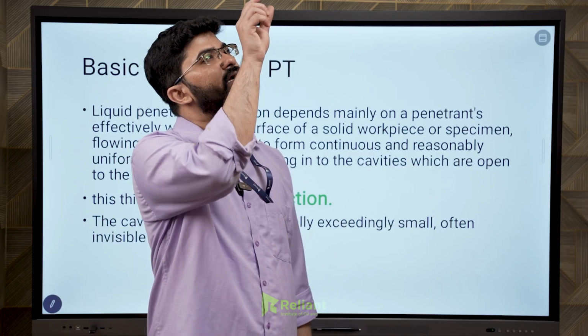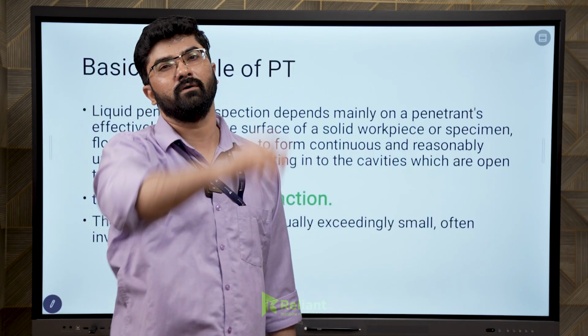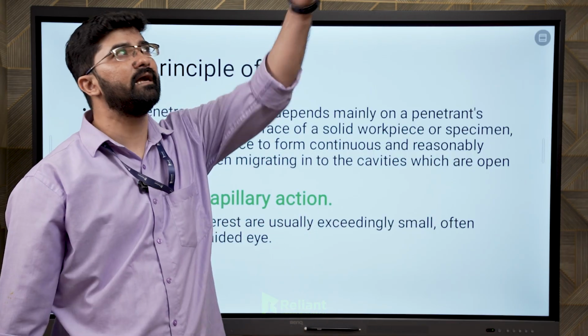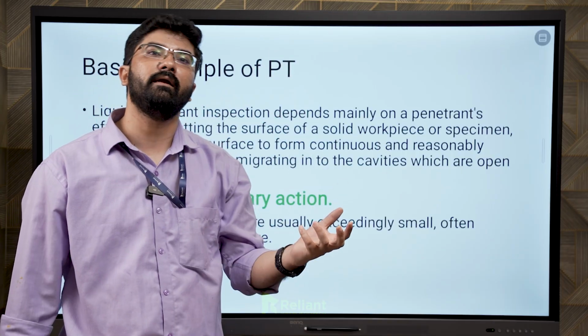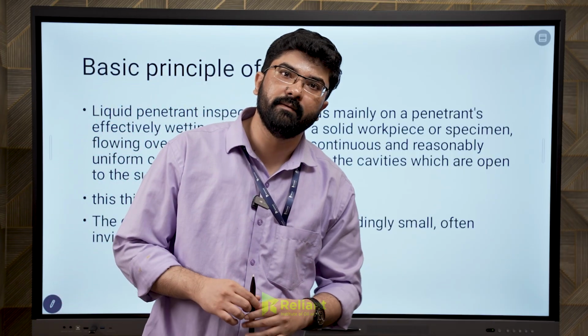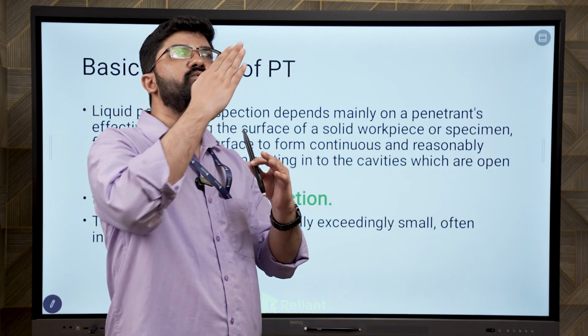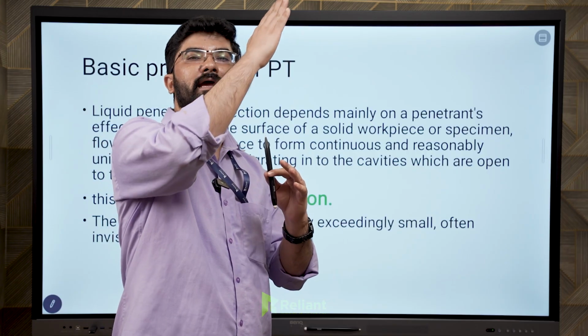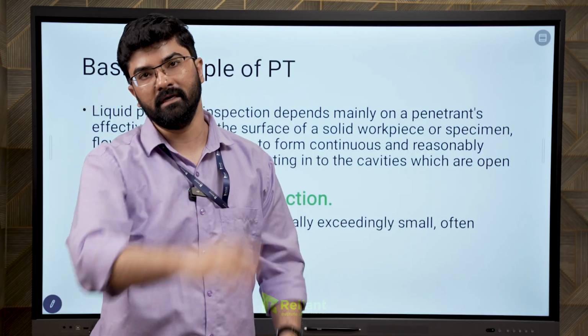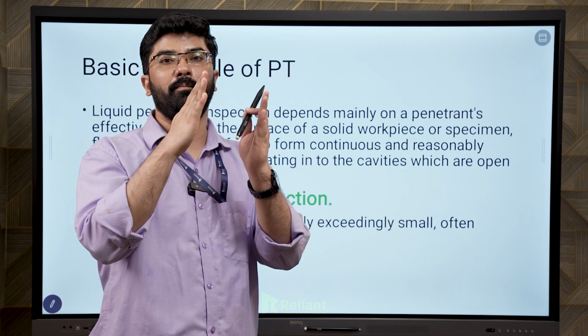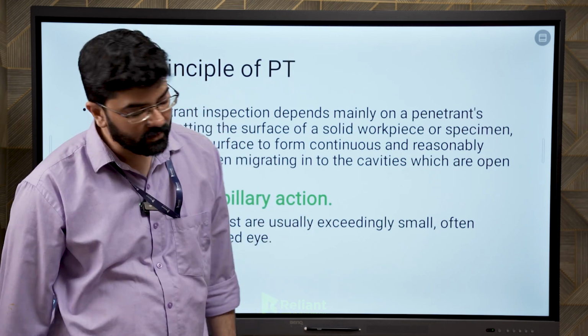In structural welding, above the head, we call it an overhead position. Even in overhead welds, you can conduct PT, penetrant testing, because the penetrant will penetrate due to the capillary action into the overhead welds if there is an open surface crack.